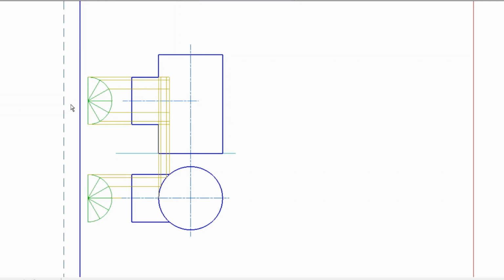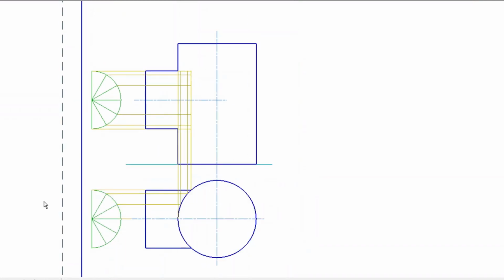This is very similar for both the grade 11s and 12s. Before you can do the developments, you have to complete the front and top view. Now the top view is already done. There's the line of penetration that runs in the top view. It's actually on that circle. But in the front view, obviously it will be some type of curve. But understand it's not difficult to do.